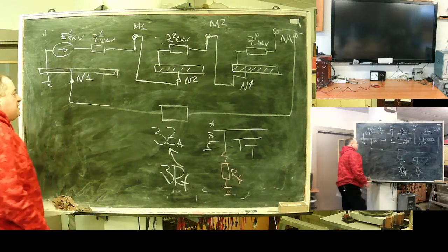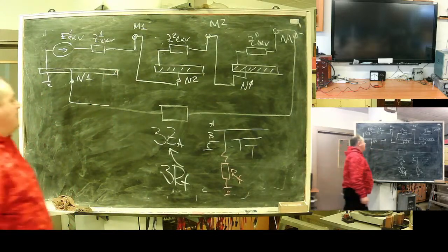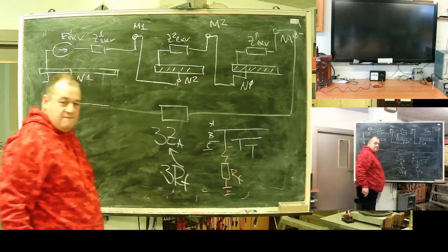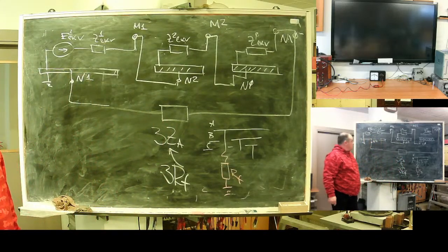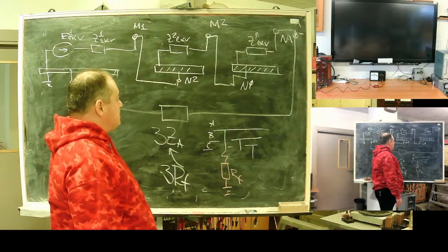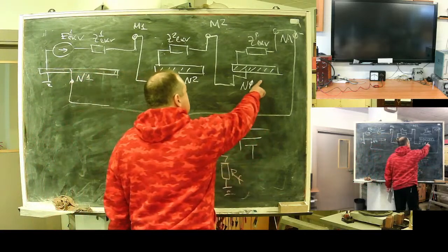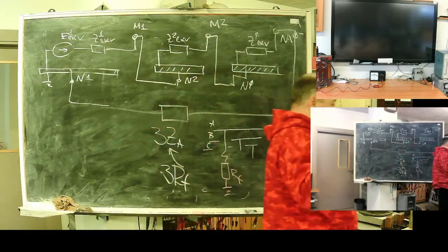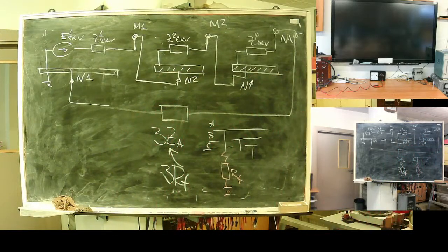It's like a symmetrical load regime. For the negative sequence, it's like a generator with opposite phase sequence attached at the fault place. And a special zero sequence. This is the calculus model for a single phase fault.